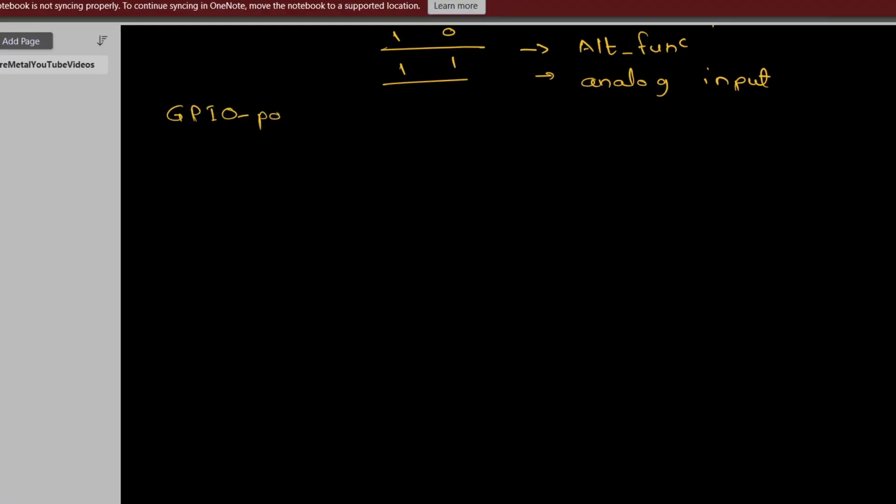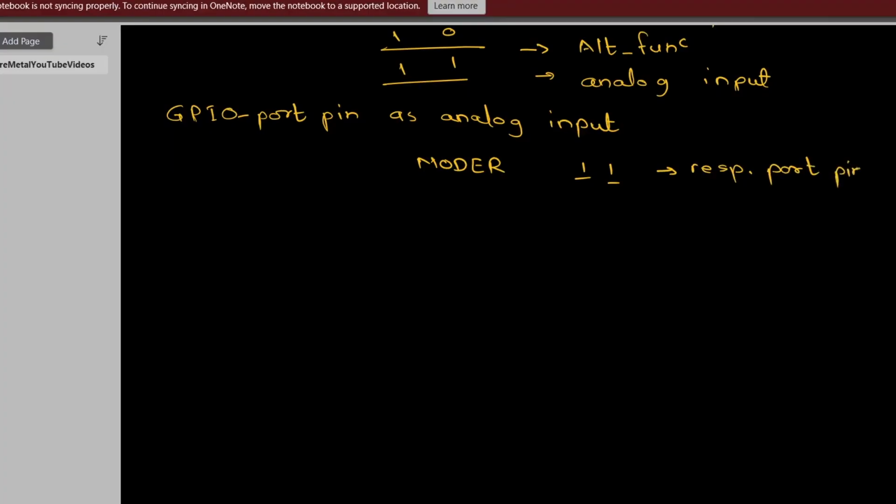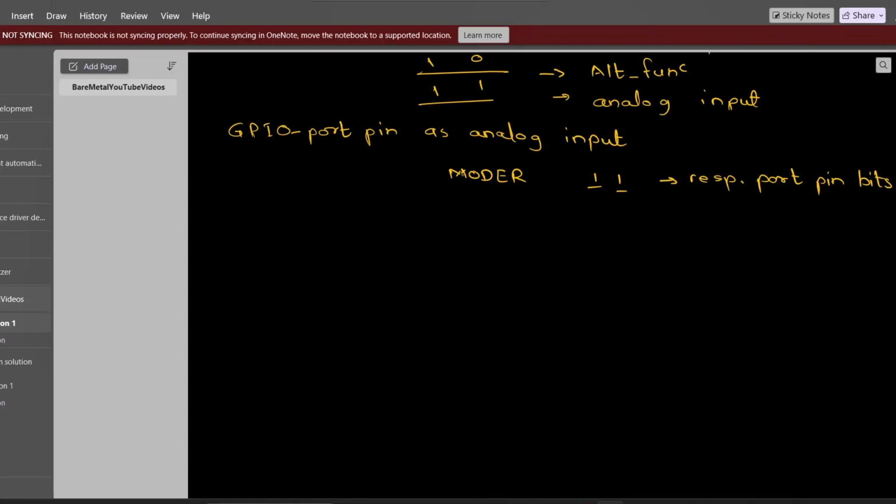So we know that we have to write 11 to the respective port pin bits in the mode register.